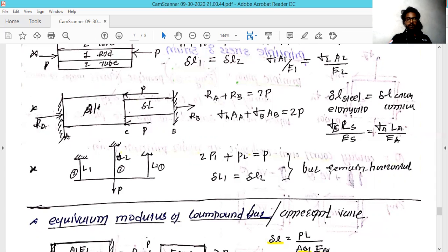So this equation you have first drawn, and now we know that the change in length of the first cross section is equal to the change in the second cross section. This condition only follows when it is mentioned that after the elongation, the horizontal bar remains horizontal. Because if it does not remain horizontal, then there may be a difference in the two end cables, which are elongated in a different fashion.